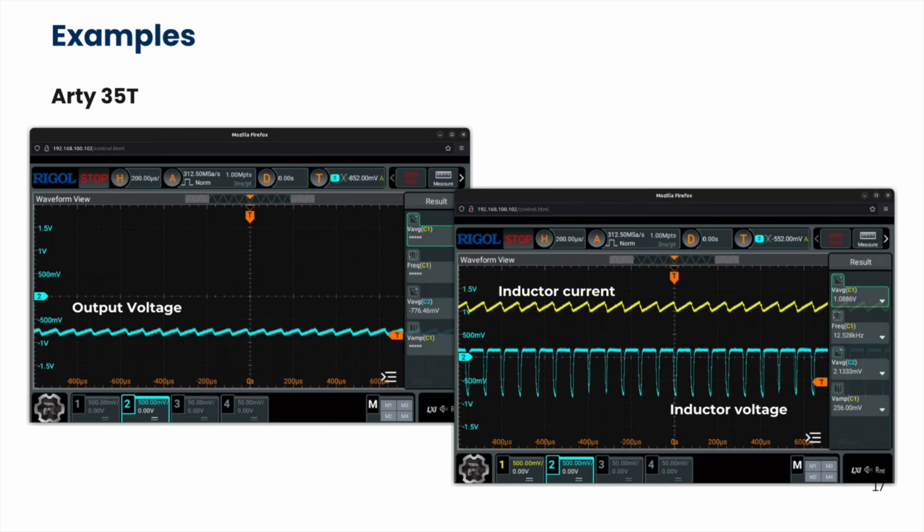On your left, you can see the output voltage of the state, which, since the buck-boost is an inverting converter, you can see that the output voltage is negative, and it has the typical ripple we can find in this kind of converter. On the other side, we have the inductor current, which is also a triangular wave, and at the top of the second capture, we can see the input voltage, which has to be a square wave. In this case, it's not a perfect square wave, not because of the model, but because of the analog output I am using.